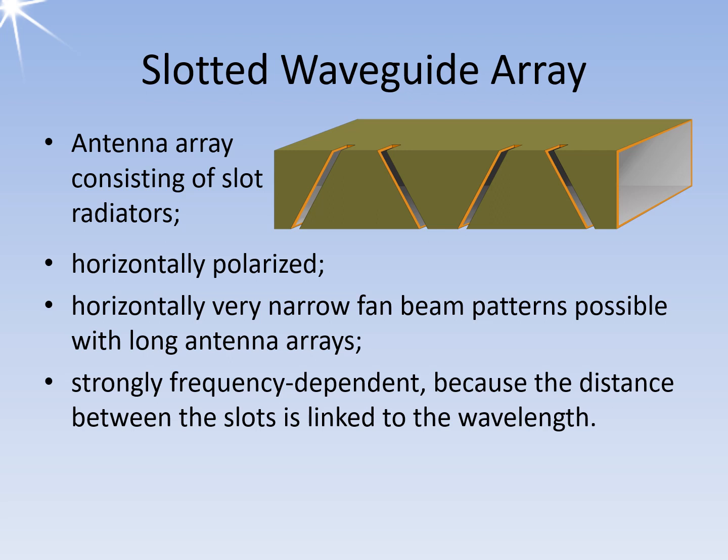The distance between slots should be half a wavelength to feed all slots with the same phase shift. However, this calculation should use the wavelength inside the waveguide, which is slightly larger than the wavelength in free space for the same frequency. A change in frequency can cause a phase difference between the slots, which leads to an electronic sweeping of the main direction of radiation. This feature is called a frequency-steered phased array, abbreviated to FSPA.